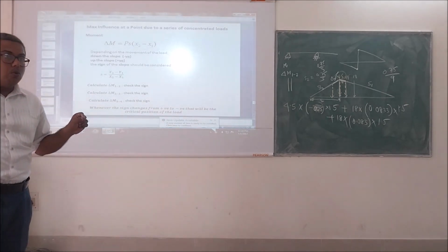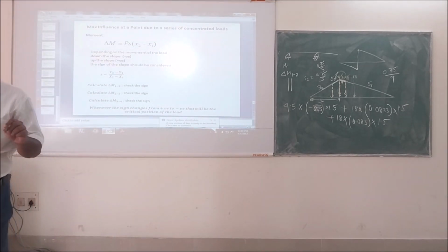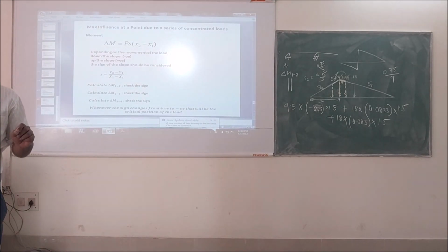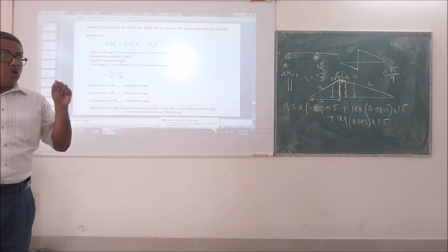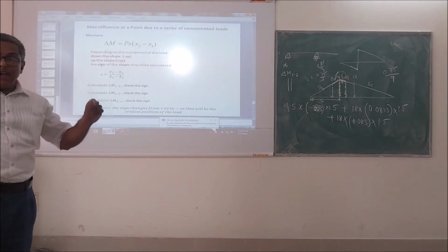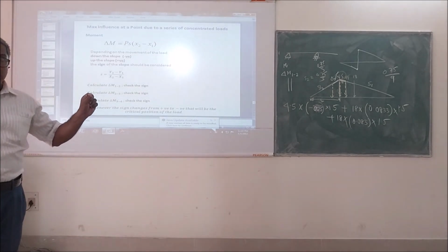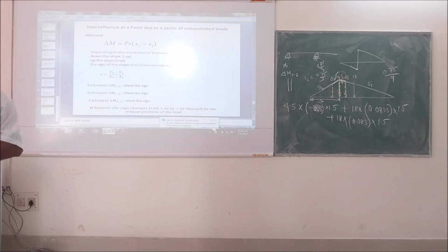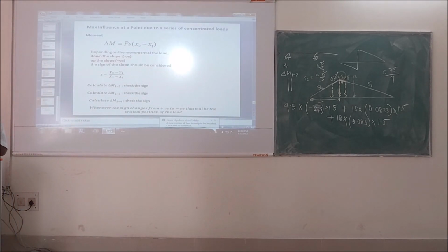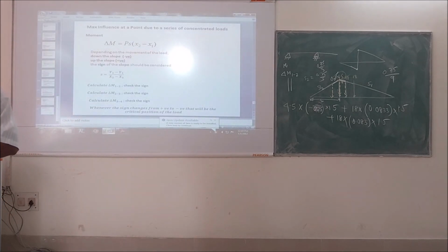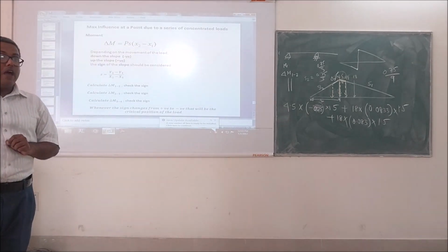What you have to do is first find out the slopes of the different straight lines, and multiply the slope with the value of the load and the changing position of the load. If there is a drop, then you consider that drop, and from positive to negative or negative to positive, you consider the sign also. If you do not consider the sign, your values will be wrong.